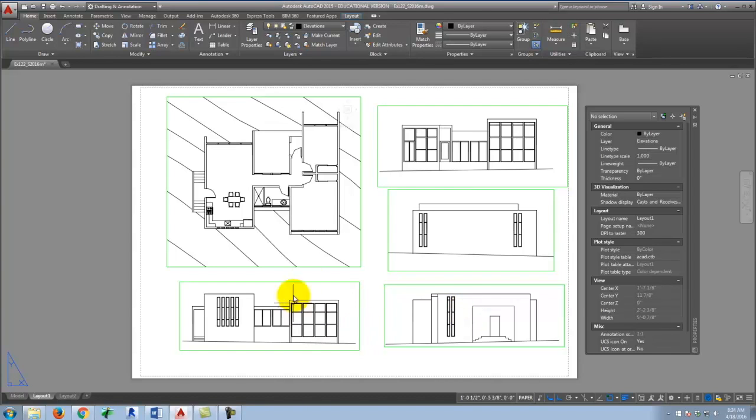No? I think everything got a lot easier because we don't have to use the MV setup anymore. Just rotating the viewports is a whole lot easier. So we're making progress. Okay? So I'm looking for this. I'm looking for no borders. Right? Make sure all of your viewport borders are on a non-printing layer. That's important. And then you'll go ahead and post the PDF by the end of class today.